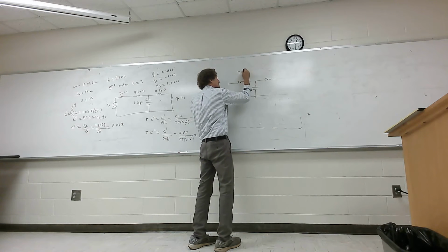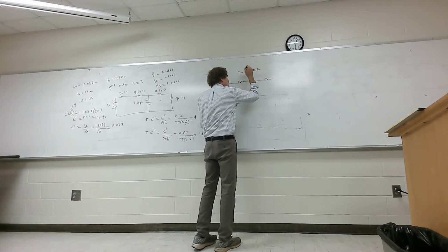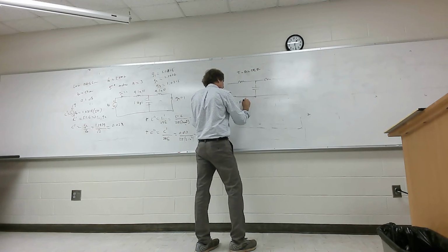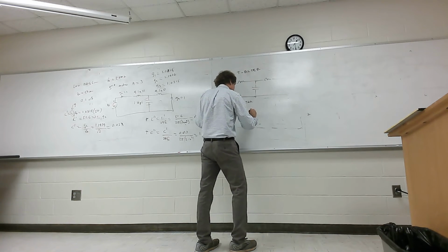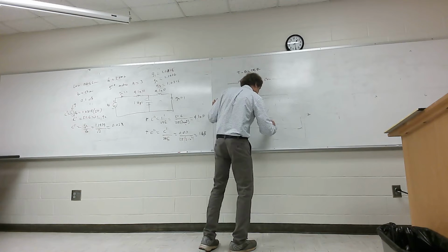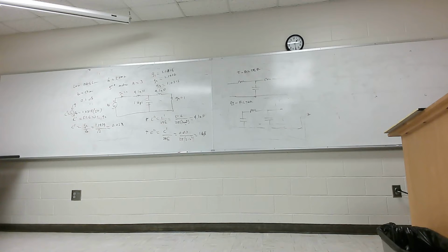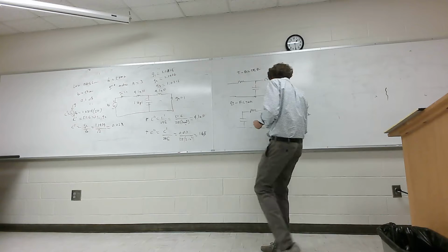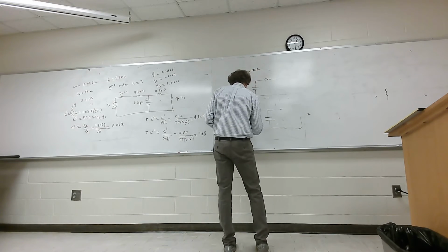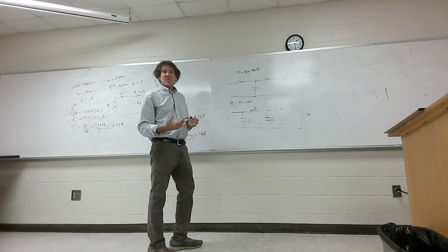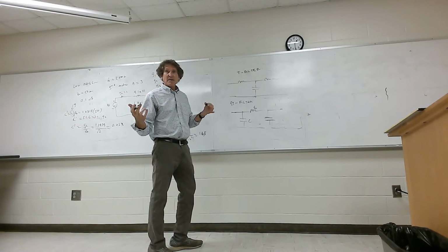This is called a T filter, by the way. Whitmer's book doesn't call it that. The other one is called a pi filter, because it looks like the symbol pi, and that's going to have a capacitor here, then an inductor in series, and a capacitor here, and the load would connect. Capacitor, inductor, capacitor. For these things, it's always an odd number of elements. Y'all follow? You're either going to have 1, 3.